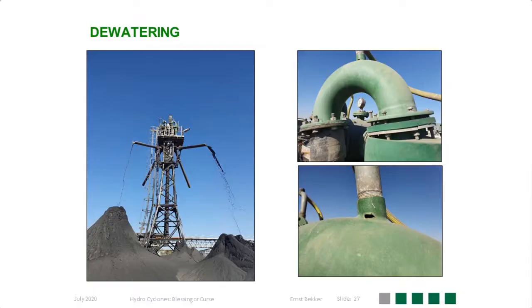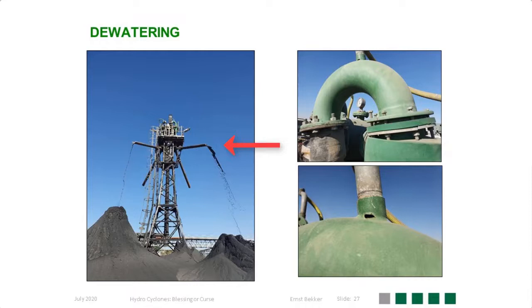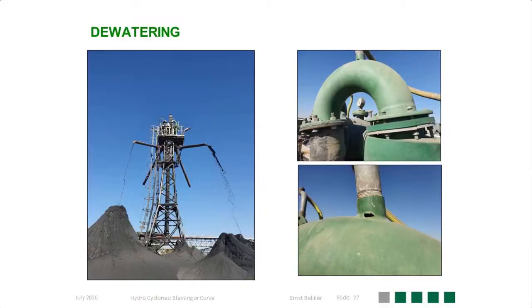The picture on the left hand side shows the installation of 2 stacker cyclones. The discharge shows a good discharge. The cyclone is operating correctly. On the same installation, the right hand cyclone is not operating correctly. And now the client is becoming frustrated, wondering what's going on, until you start to take a closer look.